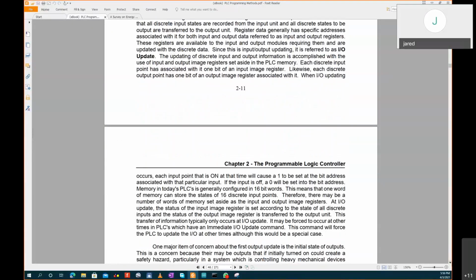Of course, you see that it will check every input. If you have 500 inputs, it will check all the inputs before it makes any decision. Then when it's checked, it updates the register, then goes to the ladder program. It now runs the ladder program in a cyclic manner. Then if a function needs to be executed, it executes the function in the first cycle. Then again it reads the inputs on the second cycle, updates the program function, then goes to the third cycle, reads the inputs, updates.